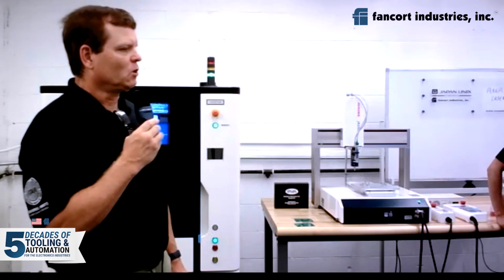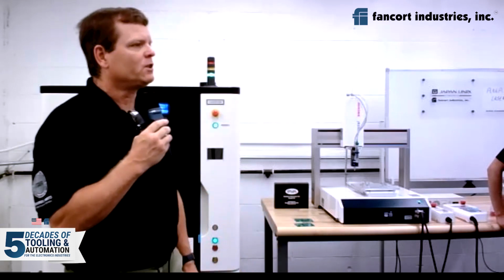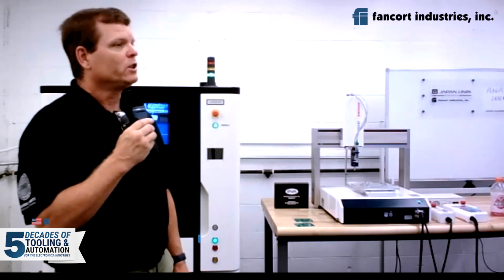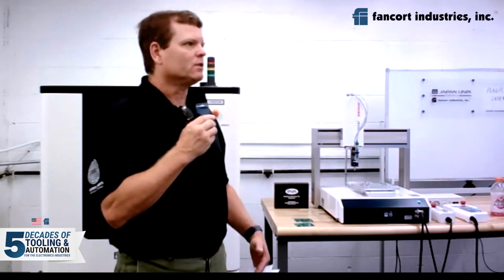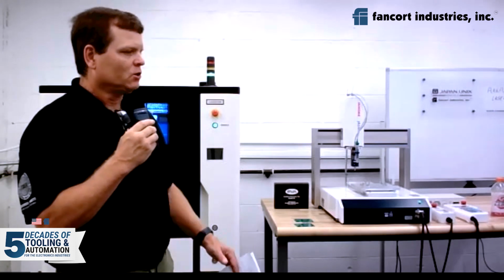We have to control the wattage we use, the temperature control with the pyrometer feature of the laser soldering system, and the time that we dwell on it. Every flux content is different, and every solder is different. So through the parameters, we certainly will be able to control that and prevent solder splash or solder explosion shock, if you will. I hope that was clear.